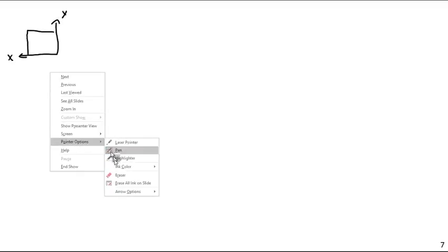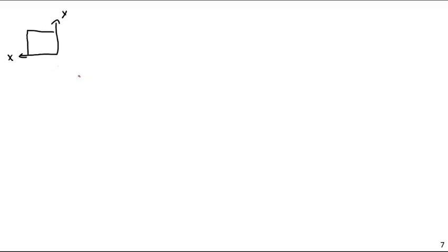So again, let us review for pressure stress. I'm going to have an element A, and if this is the x, this is the y, I'm going to have stresses as follows: a sigma longitudinal along the x-axis and a sigma hoop along the y-axis.